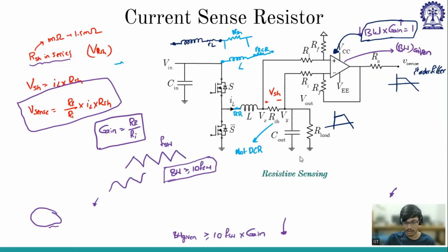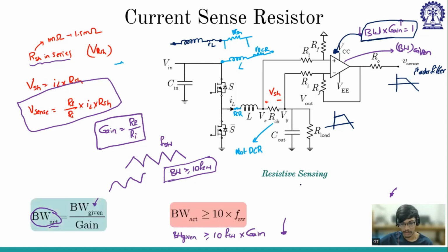Yes, sir. Okay. So this is coming from the op-amp. We cannot continuously increase the gain and expect this output will also have that ripple information. So this is the functionality of that first order filter. So we cannot operate at the higher bandwidth for higher gain.